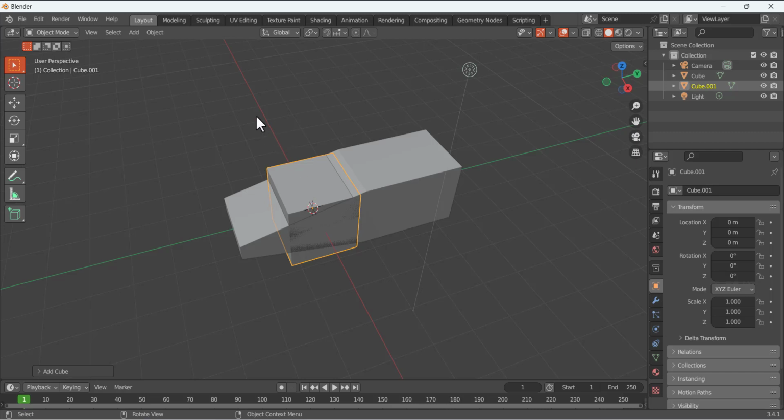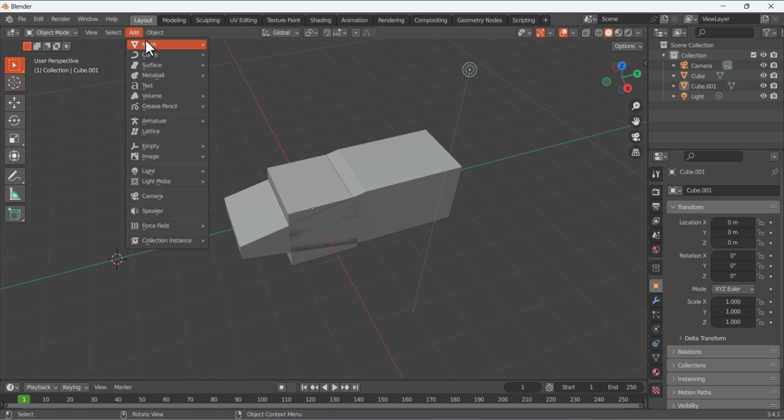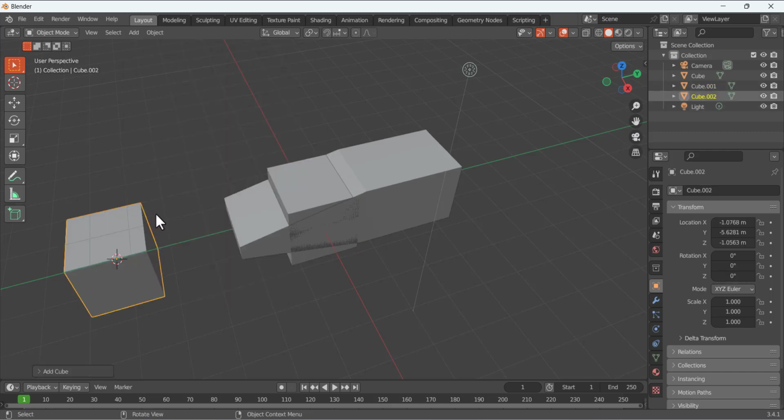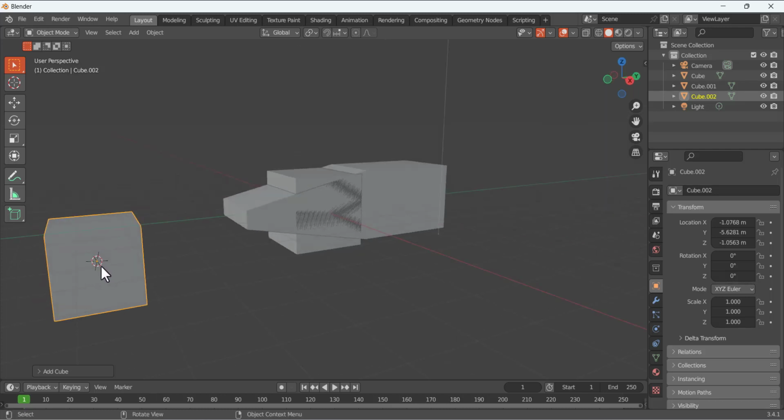How can I achieve that? We click here with the 3D cursor, and I want to place this cursor on this location. Now the location of the cursor is changed to this position. So again, go to select to deactivate the cursor command. Make the selection, and now if I add the cube, it will be added at the position of this 3D cursor.